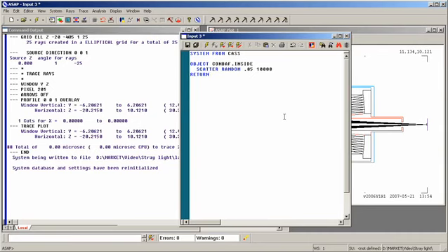I now need to define some rays that enter the telescope. We'll do this with the grid command. Grid elliptical, meaning it's an elliptical grid at the entrance to the telescope. The entrance to this telescope is located at the global coordinate z = -20. And I happen to know that the entrance aperture has a semi-diameter of 6.